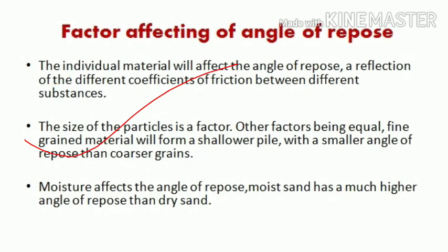If the size is coarse or fine, the angle may vary from lower to higher angles. Also, the moisture content: moist sand has a much higher angle as compared to dry sand. So there are many factors affecting the angle of repose.